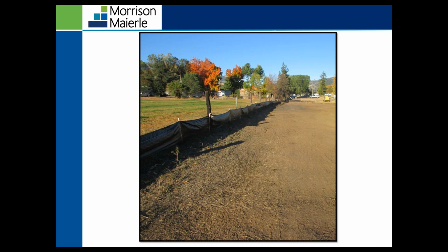Now this BMP is most effective when installed at the site perimeter, the toe of slopes, near water, wetlands, and at the pollutant sources. It's a common BMP that you see on construction sites. It's just a pain though to maintain. It requires intensive maintenance to remain effective and cannot be used in concentrated flows.